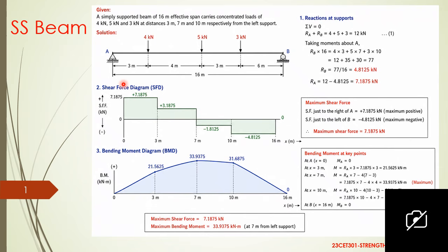Shear force means the algebraic sum of all the vertical forces on either the left or right side of the section. That means at whichever point we are going to find the shear force, we can take either the left portion or the right portion. Here I am taking the left portion. Left of A, there is no beam. Only at point A, the reaction RA is acting in the upward direction. That is plus